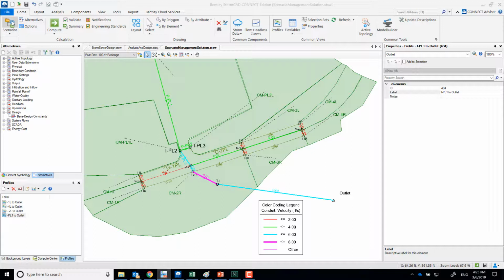And the last question, best time to make use of prototypes. We use prototypes a lot at the beginning when we were laying out elements. And if you're going to do a lot of manual input, then before you draw anything, you want to do the prototypes, right? Because if you do everything by hand and then you create a prototype, it doesn't do anything. It's only before you do that. If it's too late, then at that point you might as well just modify everything on the flex tables.